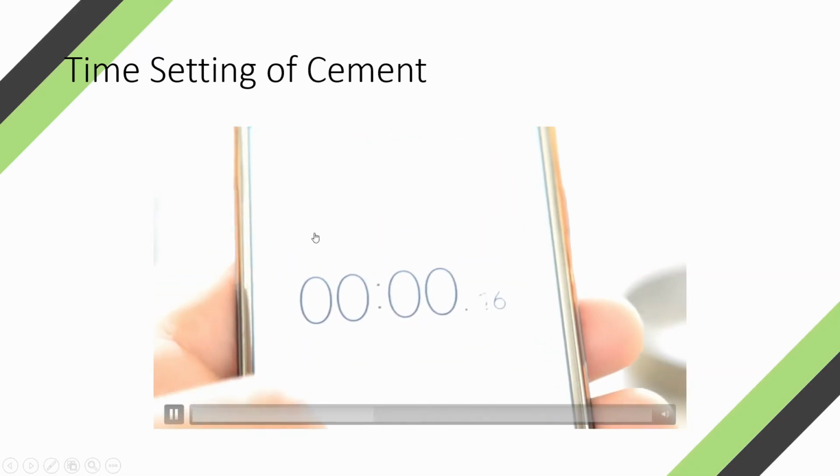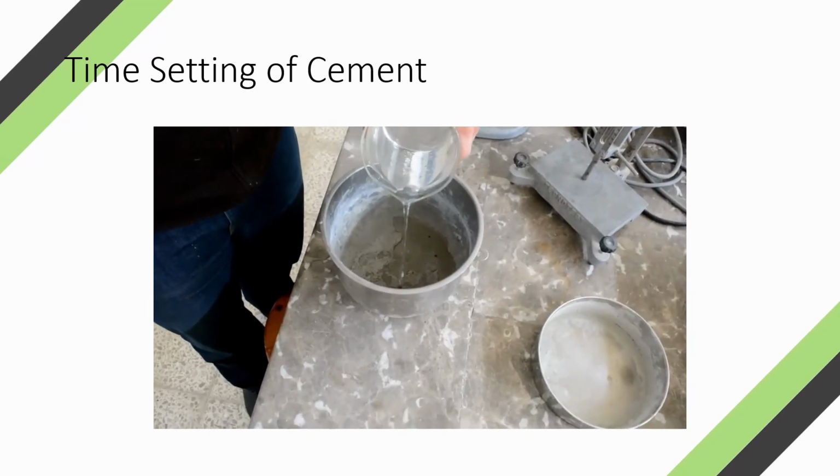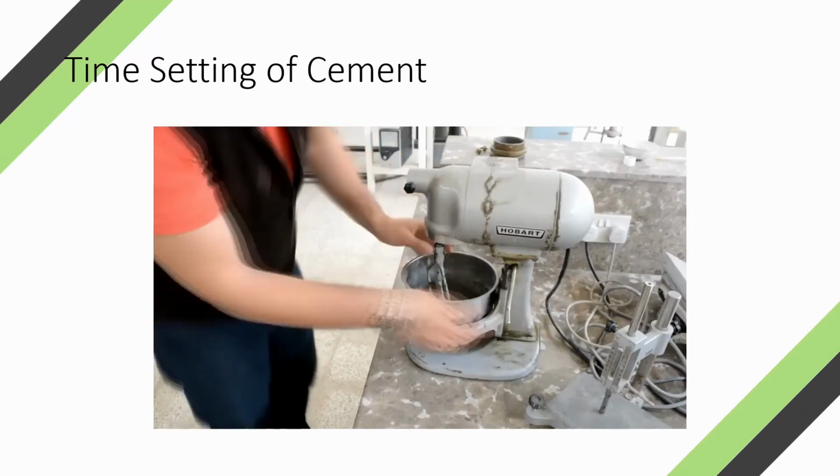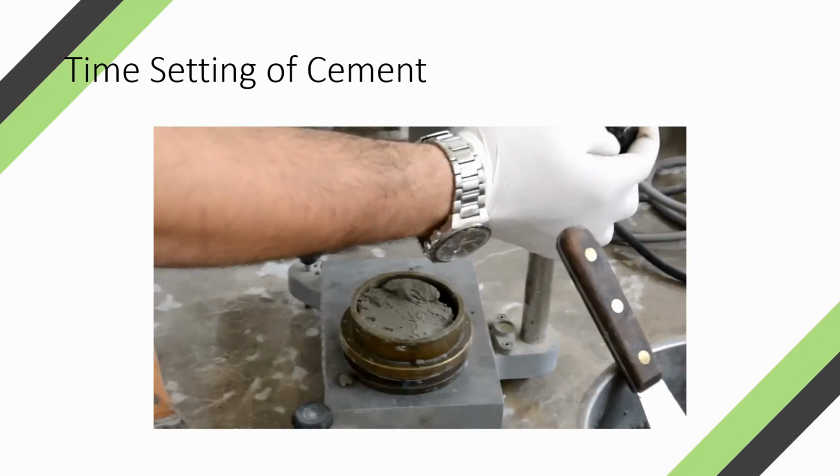Run your timer at the exact time you have added the water to the cement. You need to prepare the cement paste as we have done in the normal consistency video. Leave your paste for 30 minutes.